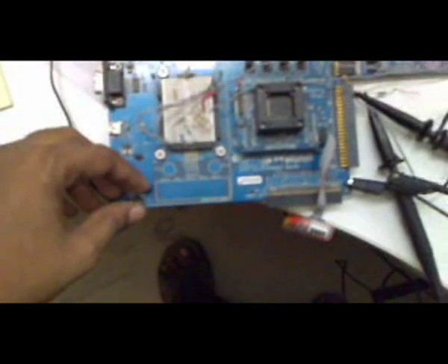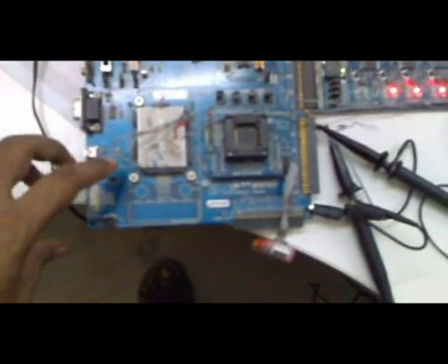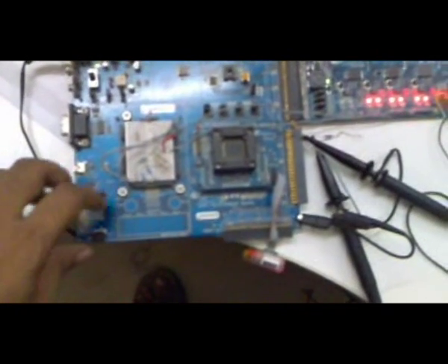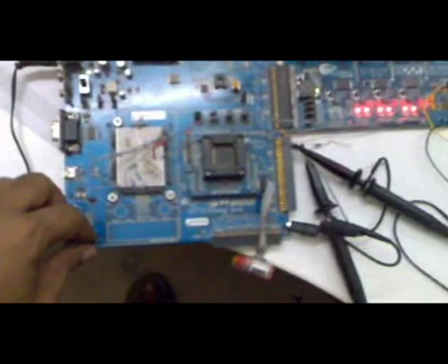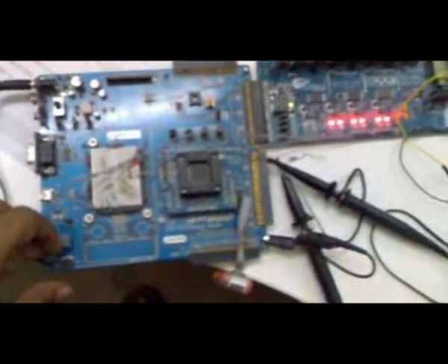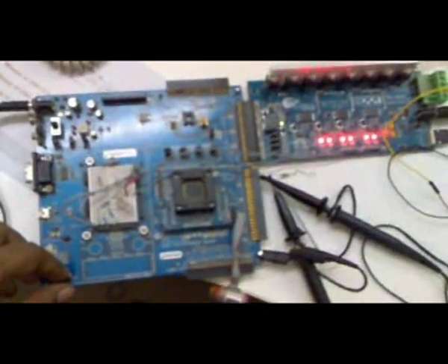Okay, now let's move on with the demonstration. To begin with, the potentiometer controlling the speed is brought down to zero position. Then the motor is started by pressing the start-stop switch in the DVK. The potentiometer is then raised slowly till the motor picks up enough torque to start rotating. And just raising it slowly. Now you can see the motor rotating.